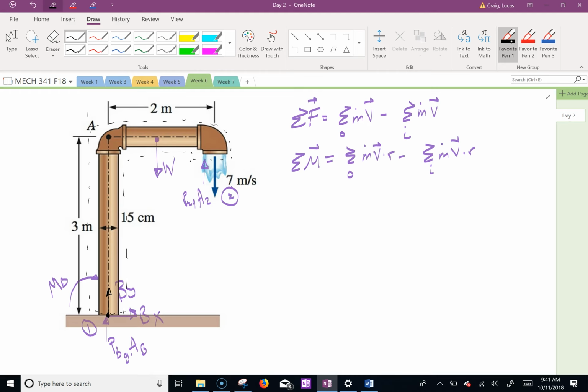So what do you lose? What's happening as the water goes through this pipe? Friction in the piping, yep, which you got to overcome. Remember, that's the minor losses, and you have major losses. Major losses are the pipe friction. The minors are the elbows. So you can figure out the pump sizes, and again, overcome gravity for shooting straight up.